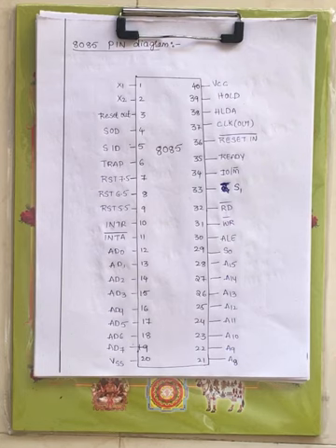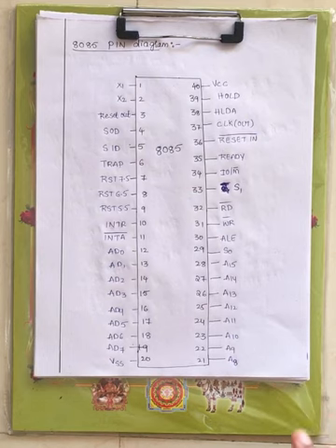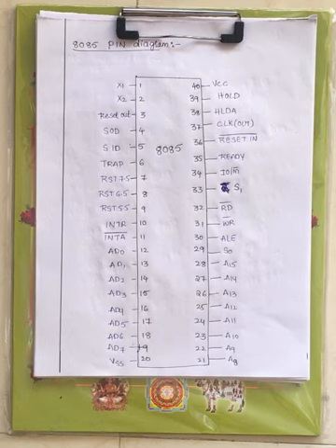Now if you see this pin diagram, we have 16-bit address lines. Bus is nothing but a set of lines. Under bus we have three different types of buses: address bus, data bus and control bus. Now the address bus is of how many lines? 16 lines are available as your address bus. That means through the address bus you can carry a 16-bit address.